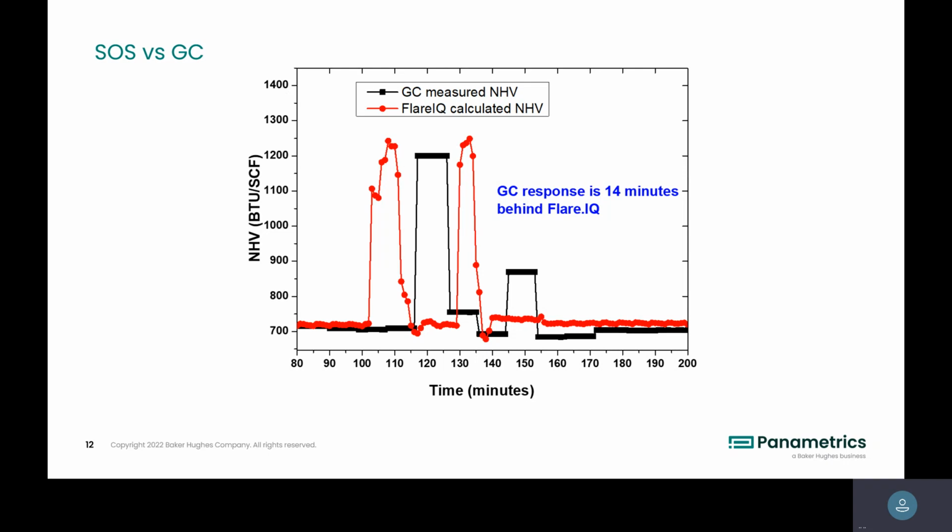an accuracy issue, not necessarily a control aspect. Those can usually be taken care of by this method. For example, if your molecular weight goes from, say, 10, which is a lot of hydrogen, to 30 or 40, your steam ratio needs to increase dramatically.